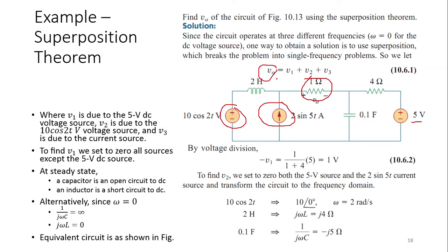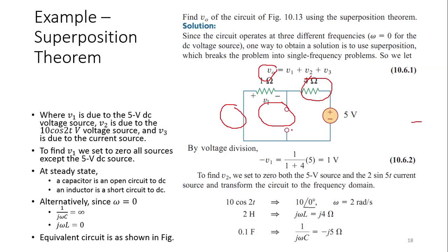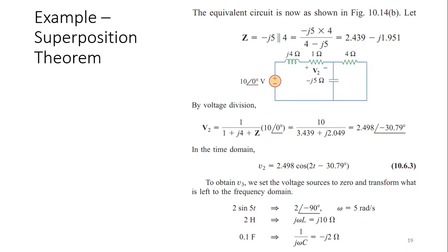we will get V naught. Solving this circuit with any other technique would be a bit messy because it contains both voltage and current sources. If we try to solve them, we need to go into some details of super mesh or super node also. So this is all about this one.